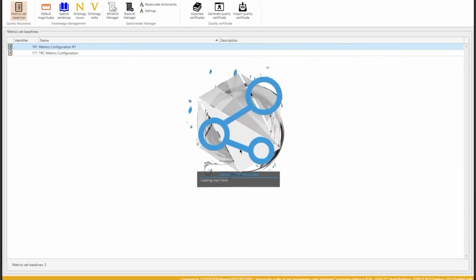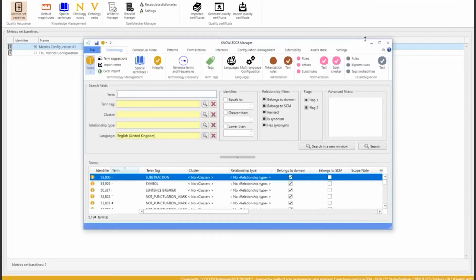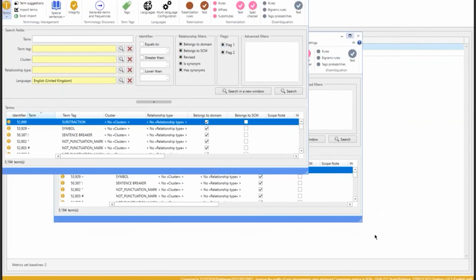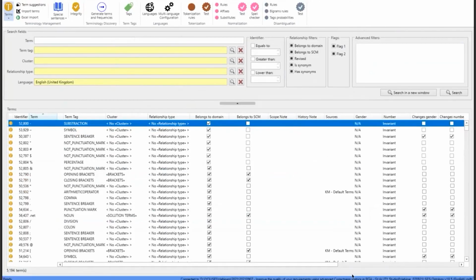Considering that these are databases that have a number of tables inside, and the number of tables increased from one version to the other, it may be harmful for compatibility to have version 18 libraries imported into version 15 databases, because some of the elements of the V18 will not find the relevant table in the V15. So my advice would be to migrate to V18.